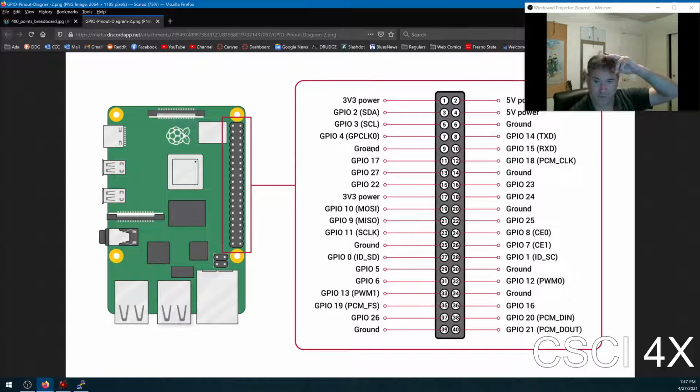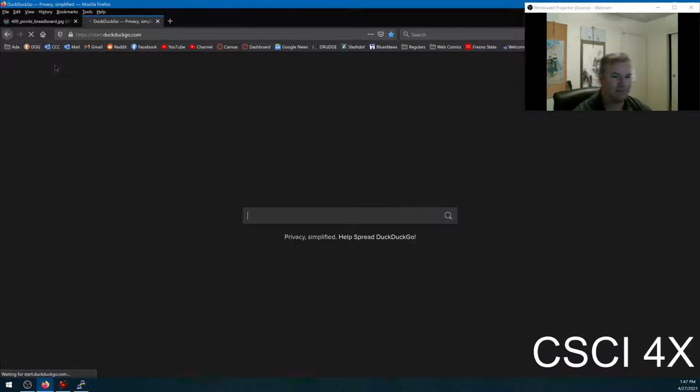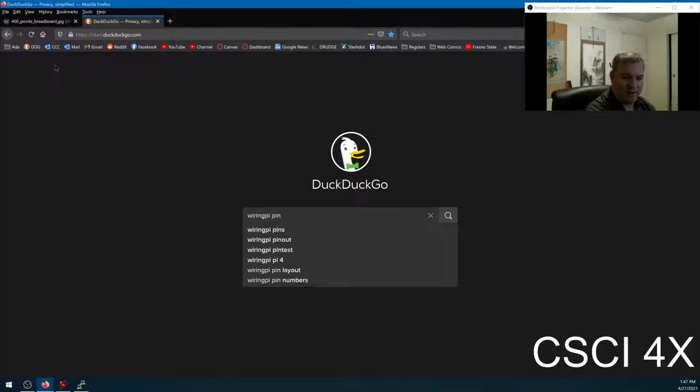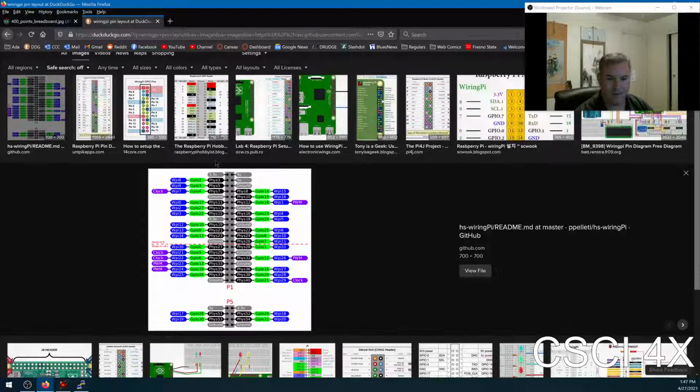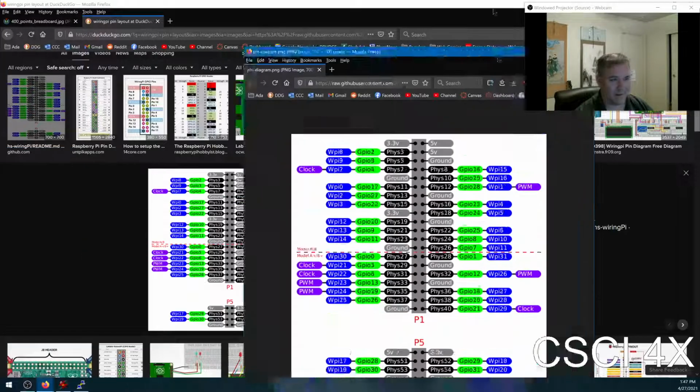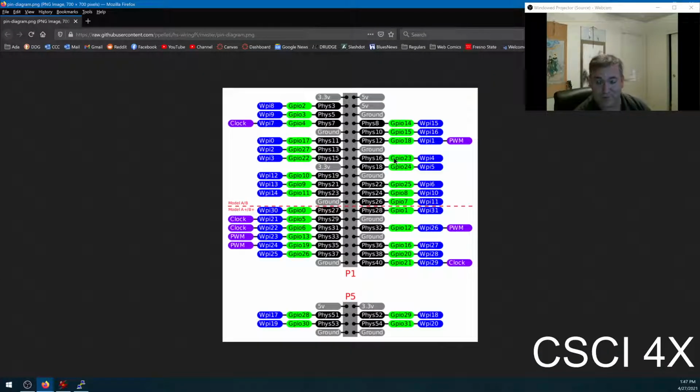These are over here. And the pin number for wiringPi is actually not the physical pin number, nor the GPIO pin numbers. These systems are numbered multiple ways, which is super annoying.